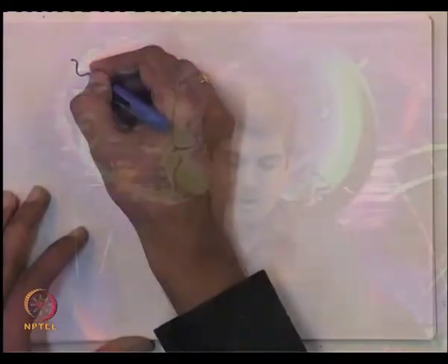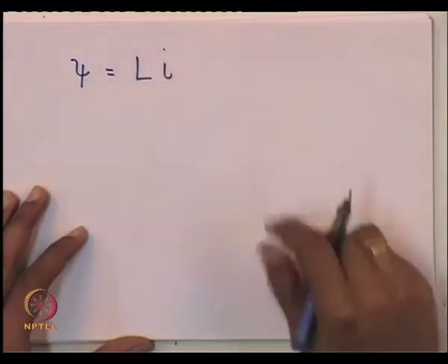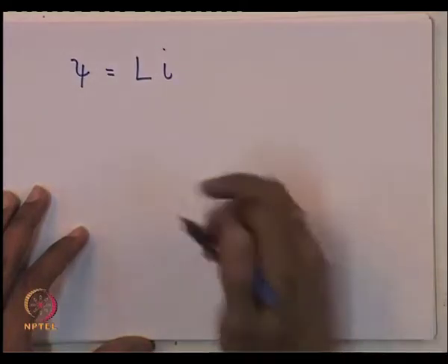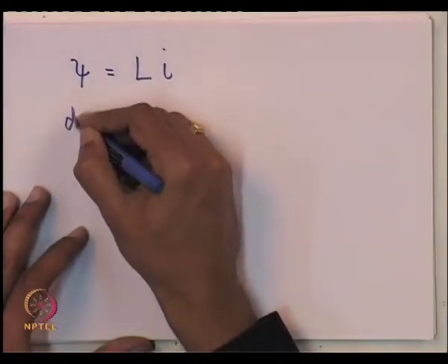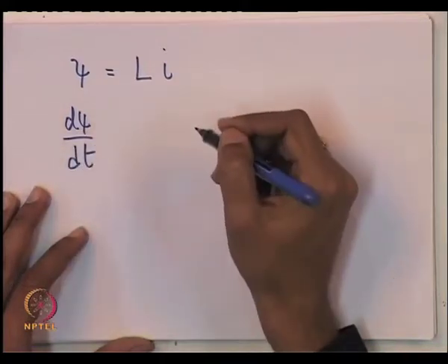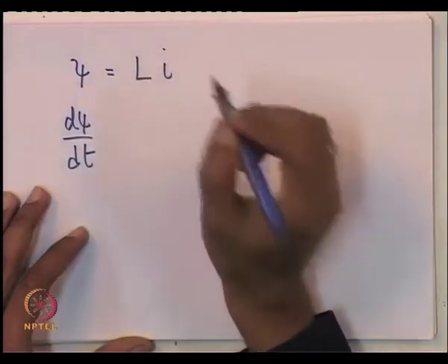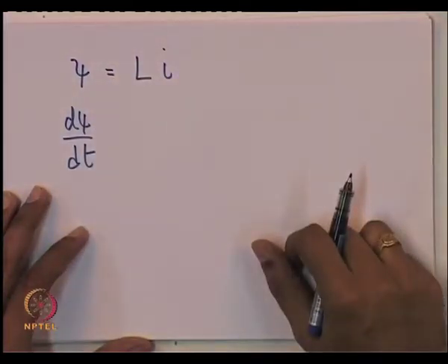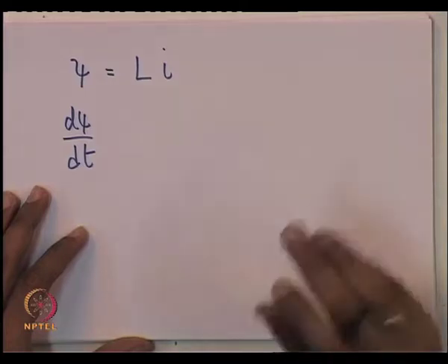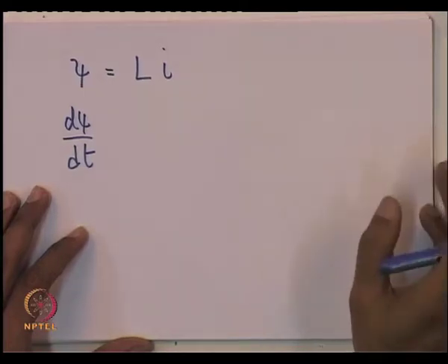of a synchronous machine, we have got what are known as the flux and the current relationships. We have got the differential equations of the fluxes. Okay. That is, we have got equations in d psi by dt. We also have got a flux current relationship. Okay. The question is, can I get the same transfer function analytically? The answer is yes, you can.